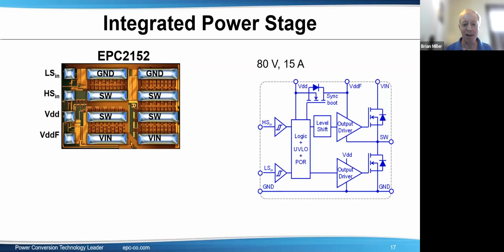Since that time, the output gate driver has really improved in function. It used to be that it had to be a 5-volt logic input. Now with these kinds of parts, you can have 3.3 or 5-volt logic, and it just works a lot better. So yes, over time, you'll see more FET and driver combinations coming out of EPC.